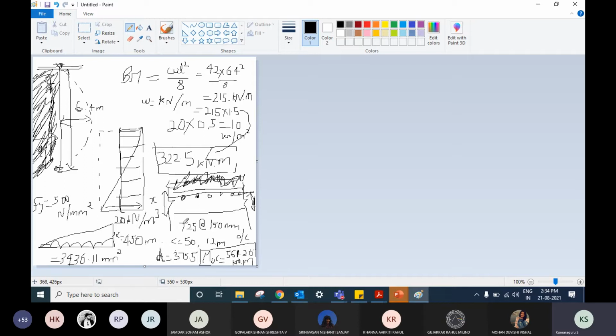So instead of 150 mm spacing, I would keep it at 225 mm. Every 25 mm increase, because 25 mm converts to 1 inch, and it's very easy on site to move something like 1 inch, instead of 5 mm or 10 mm. So you need to have some practical considerations also. Let's jump 25 mm. Instead of 150, go for 175 mm spacing, 200 mm spacing, or 225, 250, 275, 300, something of that range.